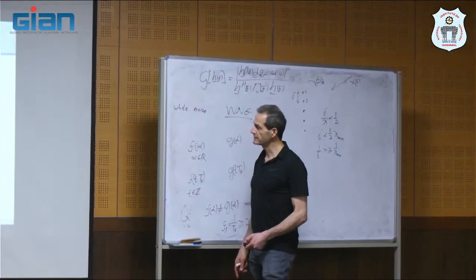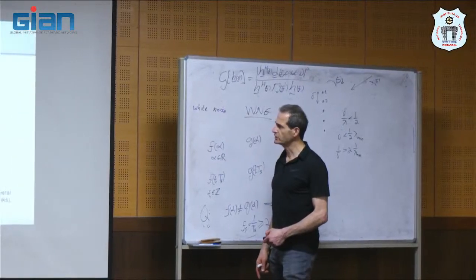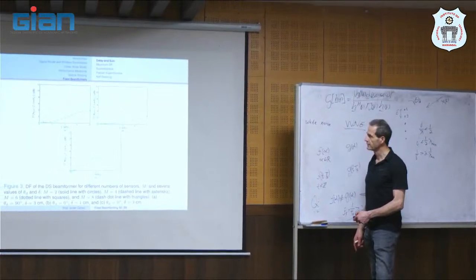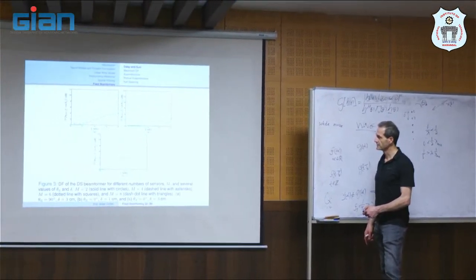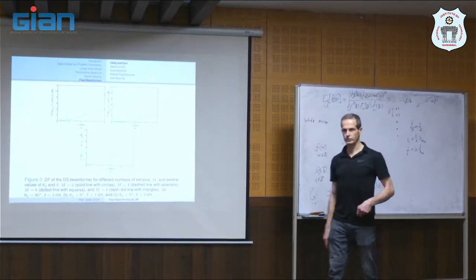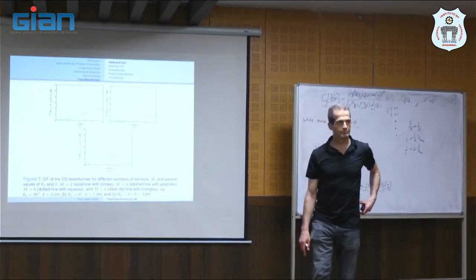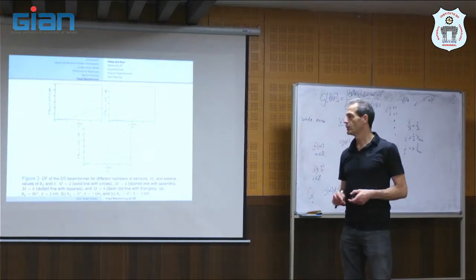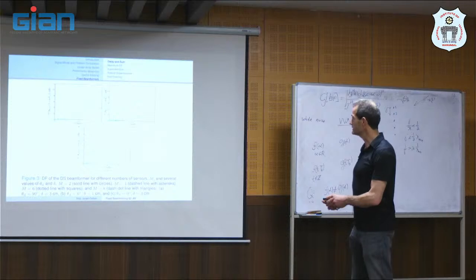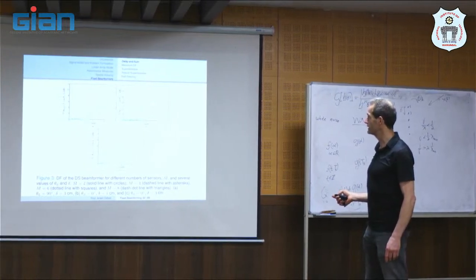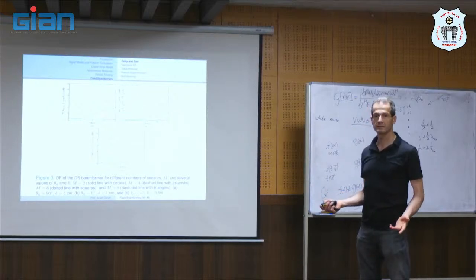And then we see something strange. Initially the directivity increases as we increase the frequency, but then it decreases. Why in the first 2 cases do we have an increase of the directivity when the frequency increases?